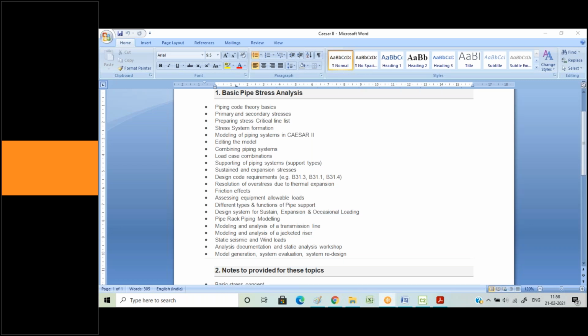At times it is required that we place a support below the line, but actually it cannot be a rigid support. So then we call the spring, because we always believe that spring is that innocent child who will serve our requirement, and he will even help us by not increasing the stress in the line. So then is when we call that spring guy, and he does the job. So let's not get into that first.